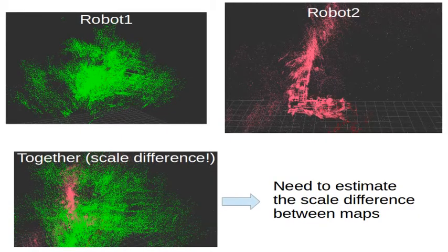It is important to note that since only images from a monocular camera are used, it is impossible to estimate the absolute scale of a map. That means it is impossible to know what distance in the constructed map corresponds to 1 meter in the real world. At the initialization of the SLAM algorithm, some arbitrary distance in the constructed map is set to the distance 1. This is different for each initialization.